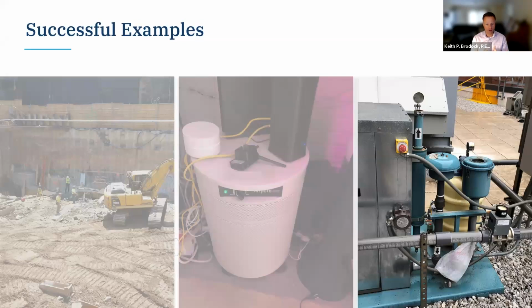So we collected a couple sets of data, and we were able to show there's actually no vapor intrusion occurring here. There's really no opportunity for vapor intrusion to occur because the soil gas concentrations are so low at this point that the other source area must have gotten cleaned up with some of the redevelopment that's occurred. And so we're able, at this point, to turn everything off.